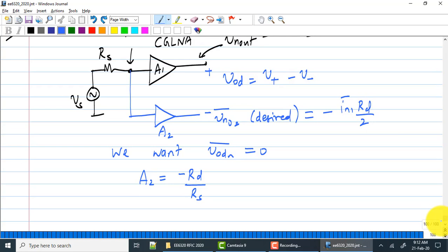Okay. So first question, what amplifier structure should we think of? So remember that the three most popular amplifier structures are the common gate, common drain, and common source. The common source amplifier can give you high input impedance, which is what we want here. If you put in a common gate structure, it will give you low input impedance. It will change the input impedance from 50 ohms to something else. We do not want that. So common gate is ruled out.